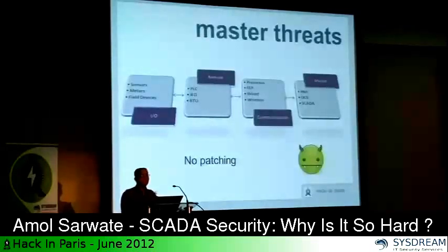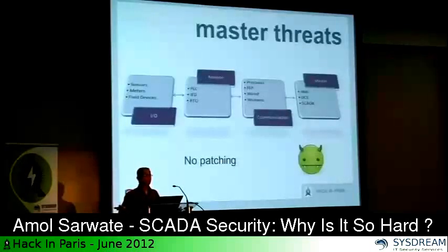So if Microsoft releases a patch and my SCADA software vendor doesn't give me any guidance on what to do with it, I won't apply the patch, because the patch could cause something wrong with the working of the SCADA software, causing power disruption or something really bad. As a result, none of these systems are patched, forever.